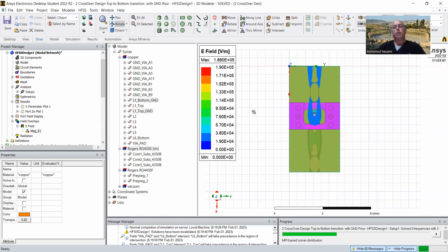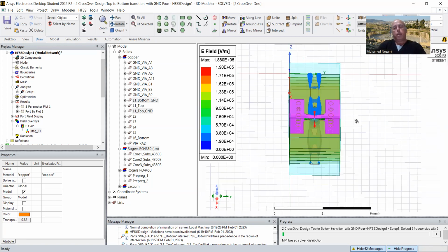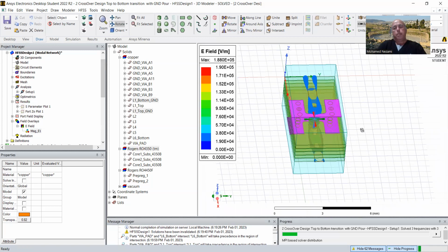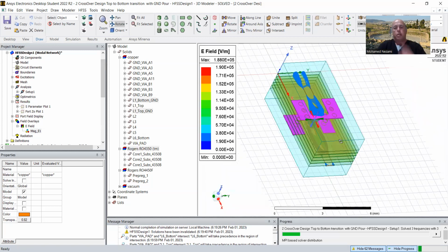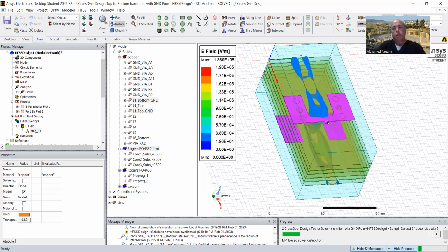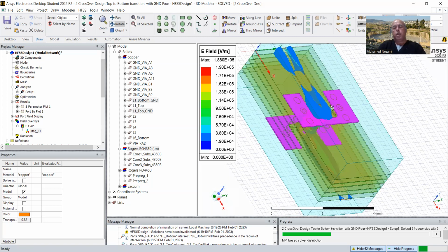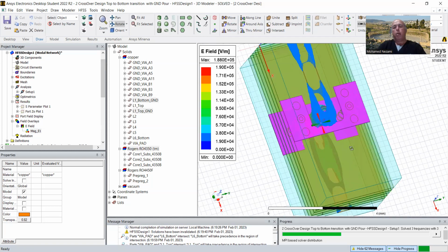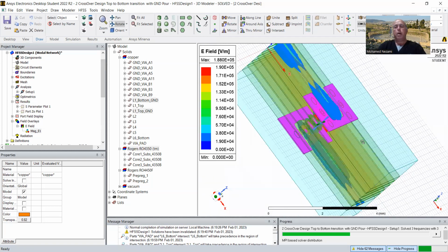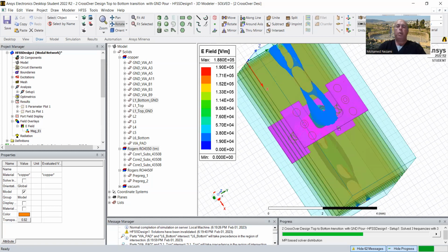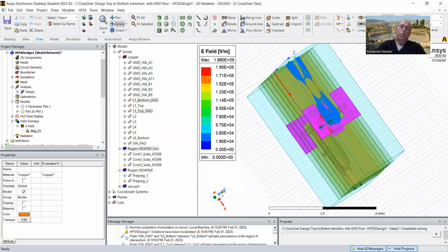They learn almost intuitively that we need a copper pour in this area and we need ground vias. Even if they're not RF engineers, over the years they get so much feedback from microwave engineers that they become really good at knowing where to put these things.